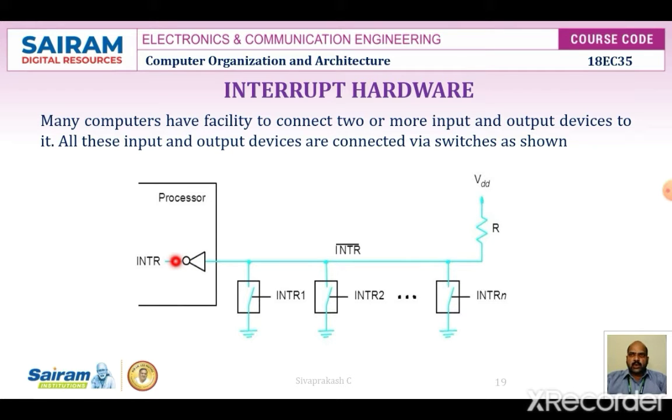And this value of INTR is a logical OR, so the requests from the individual devices are additive: INTR1 plus INTR2 plus, etc., INTRN. A special gate known as an open collector or an open drain is used to do the operation of the INTR line.